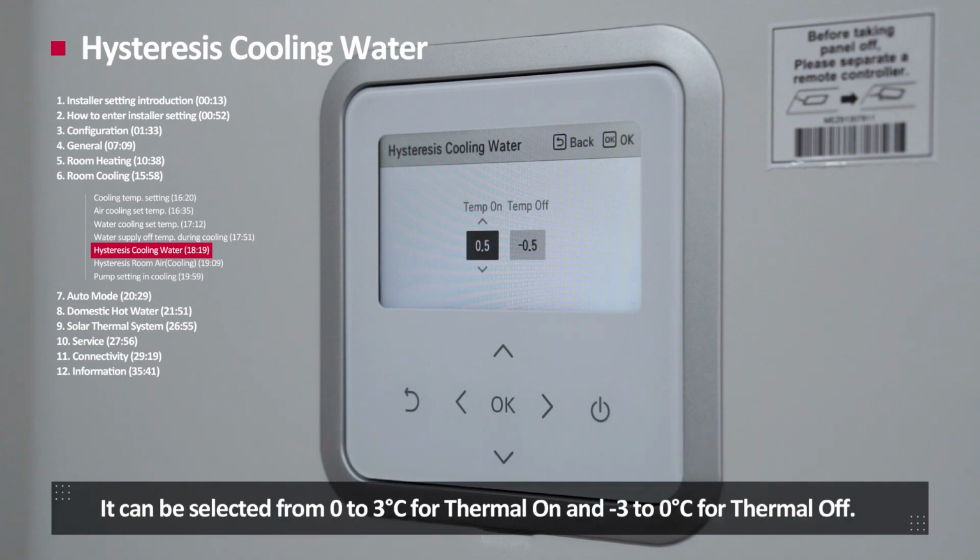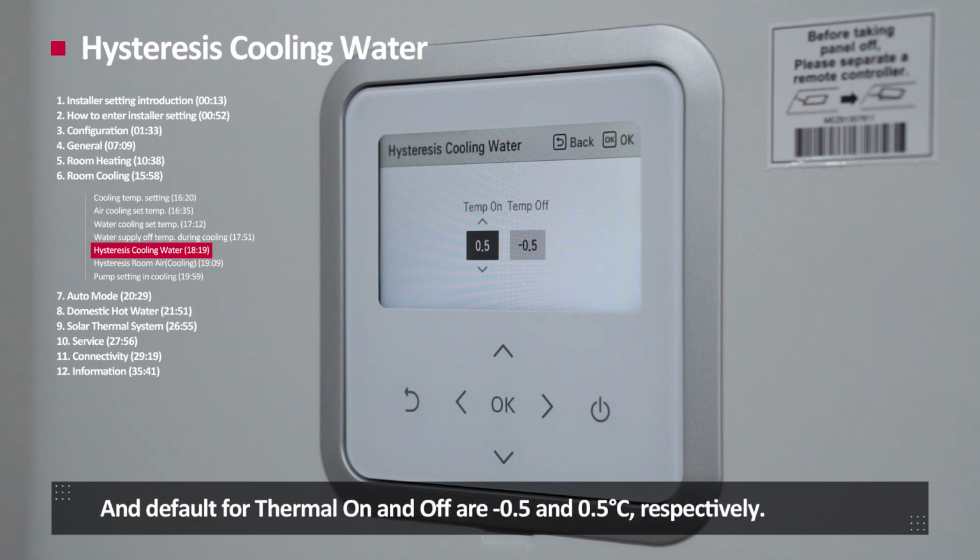It can be selected from 0 to 3 degrees Celsius for thermal on, and minus 3 to 0 degrees Celsius for thermal off. And default for thermal on and off are negative 0.5 and 0.5 degrees Celsius respectively.